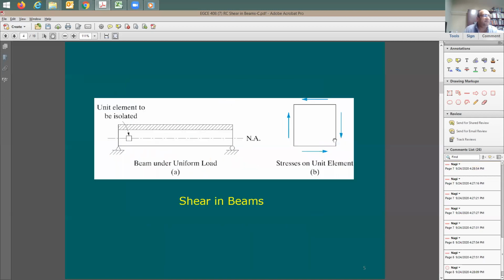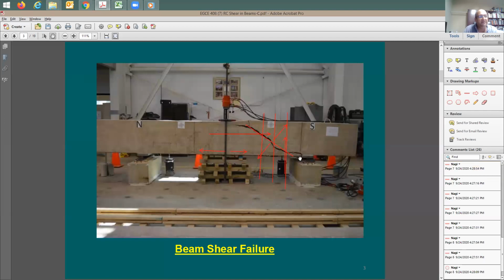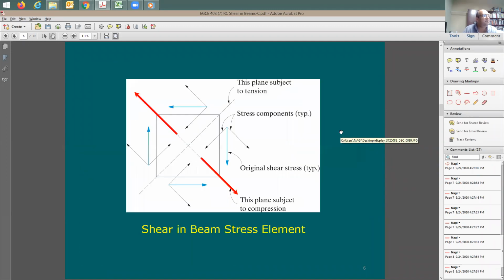Also look at this crack in previous lectures or pictures here. Look at this piece here. If you take a diagonal line, this piece is very strong. It is actually part of the support. If you want to break it, you just put pressure. It will never crack in a vertical section here, but it is going to do it at 45 degrees. Okay, so good, all right.